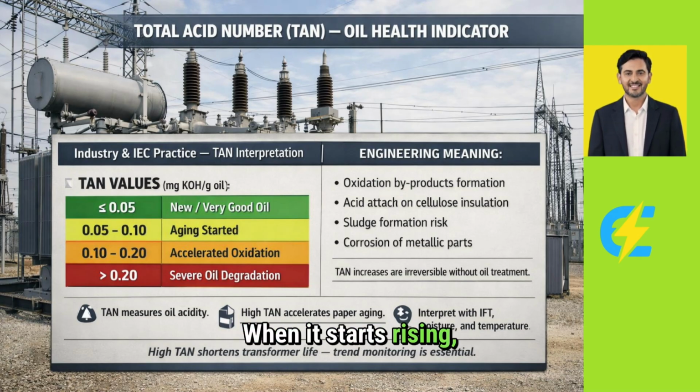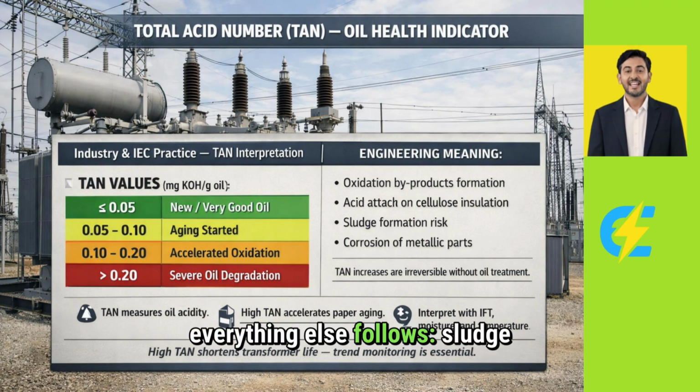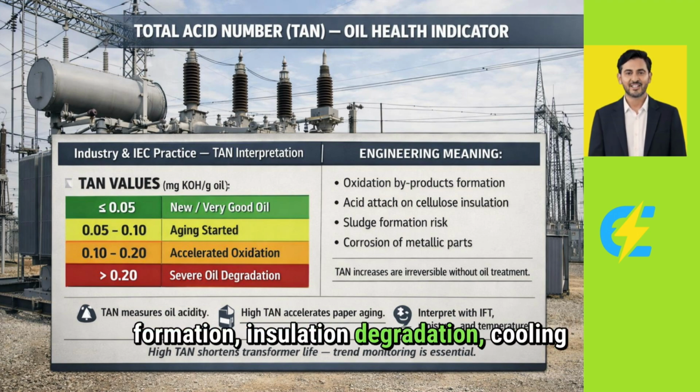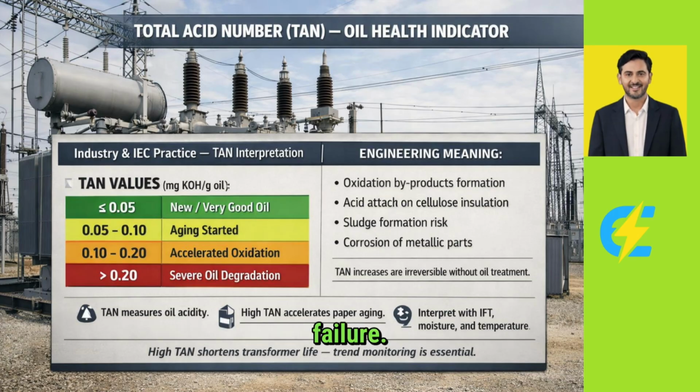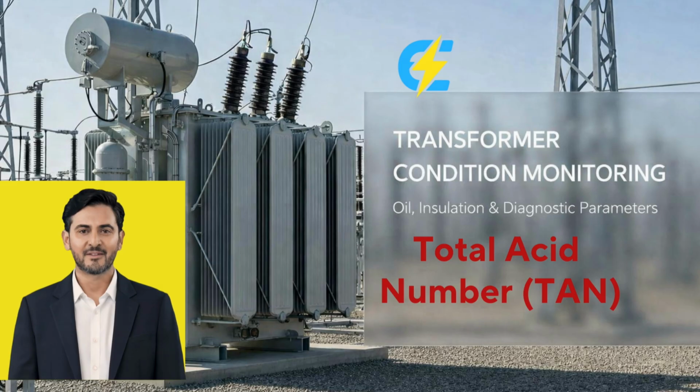When it starts rising, everything else follows. Sludge formation, insulation degradation, cooling problems, and eventually transformer failure. Ignoring rising TAN shortens transformer life because it represents the beginning of the end. But catching it early, understanding what it means, and taking timely action, that's how you extend transformer life and avoid costly failures. TAN doesn't lie and it doesn't wait. The question is, are you listening?